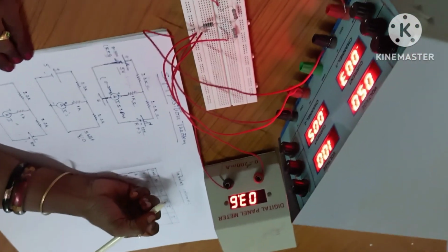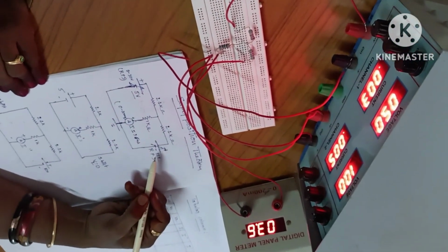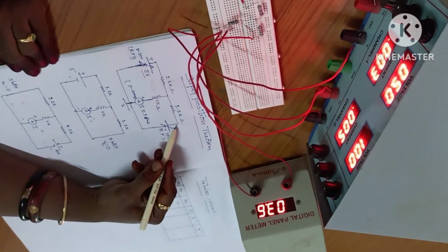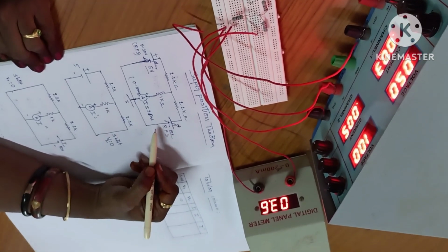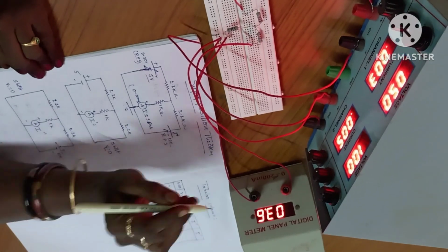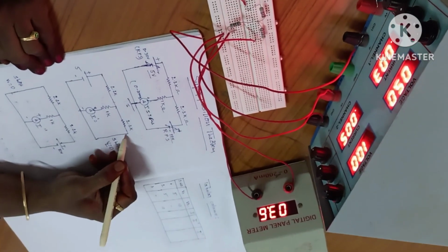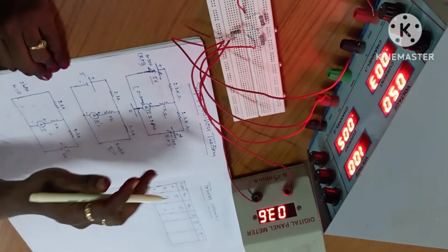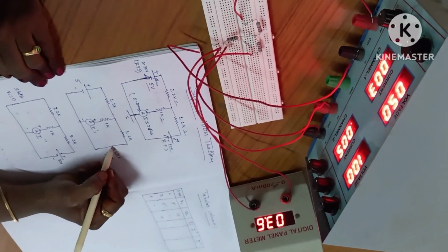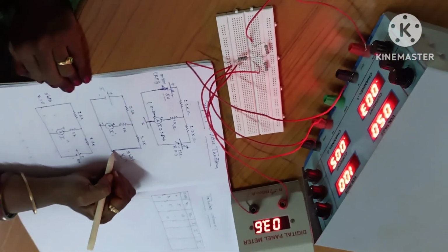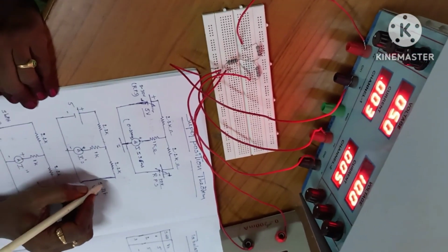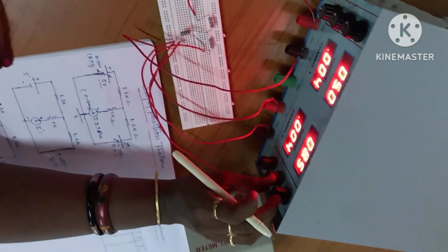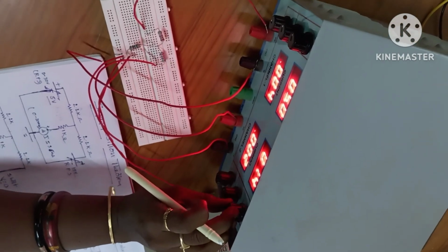According to the superposition theorem, now we are going to short one branch, I mean one supply, the regulated power supply or voltage source. Short means making the voltage zero. So in the second part, to make this a short circuit, we are eliminating one voltage source. Eliminating means making the voltage source equal to 0.